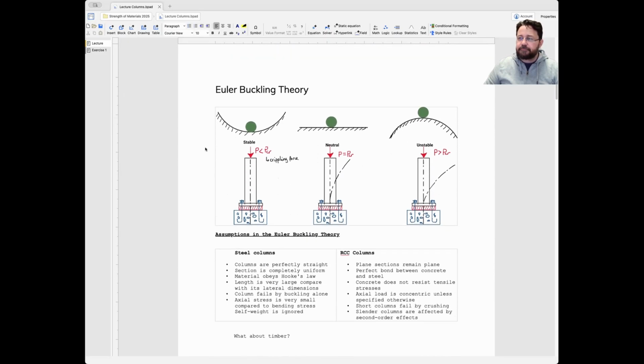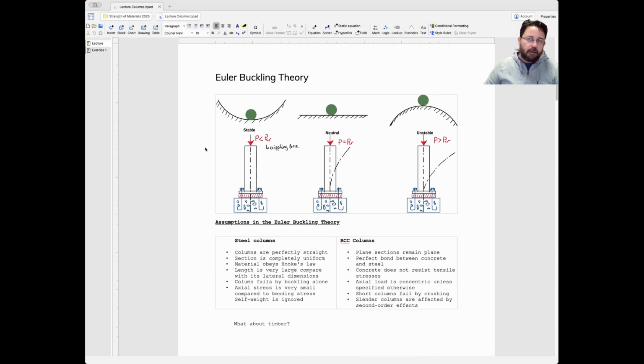But then this guy Euler said that columns, yes, they deform, they buckle, but not because of what we think. Buckling, how the column deforms, happens because of a matter of equilibrium, not a matter of force application, because the same force applied to the column at the centroidal axis, if you move it somewhere to the left or to the right, can be disastrous.